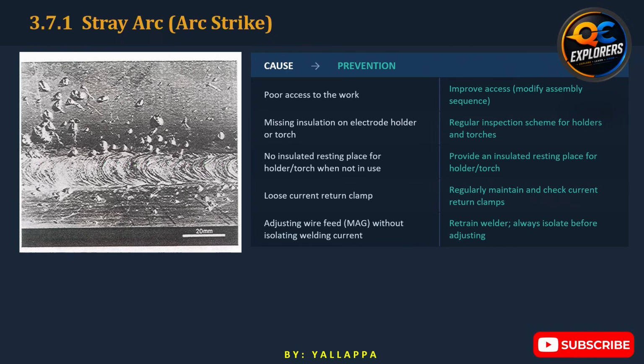That region may contain microcracks. Under fatigue or dynamic loading, those cracks can become significant. The presentation therefore recommends controlled removal by grinding rather than simply welding over the damaged area. The reason is straightforward. Welding over the arc strike introduces additional heat, creates another heat-affected zone and can complicate the repair. After grinding, suitable surface examination such as magnetic particle inspection or dye-penetrant examination may be required to confirm that